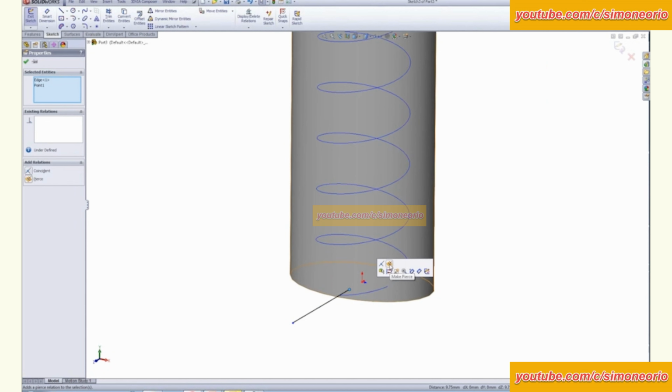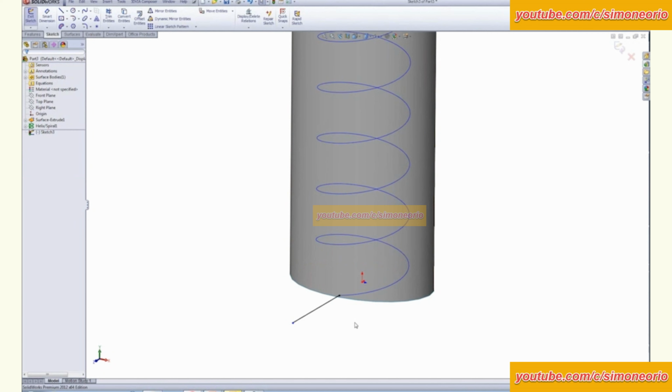The Pierce relation is a 3D relationship. A lot of times people will go back and try to use coincident. Well, one of the things you need to think of is when you're extruding or sweeping or lofting something out in 3D space, your 2D profile needs to be solved for every little integral along the path. And sometimes things like horizontals, verticals, and coincidence can only be solved in 2D space. So keep in mind when you're doing a sweep or a loft along a 3D curve that you want a Pierce relation rather than a coincident or some other 2D style relation. Parallels and perpendiculars and things of that nature are better within your 2D profile sketches.